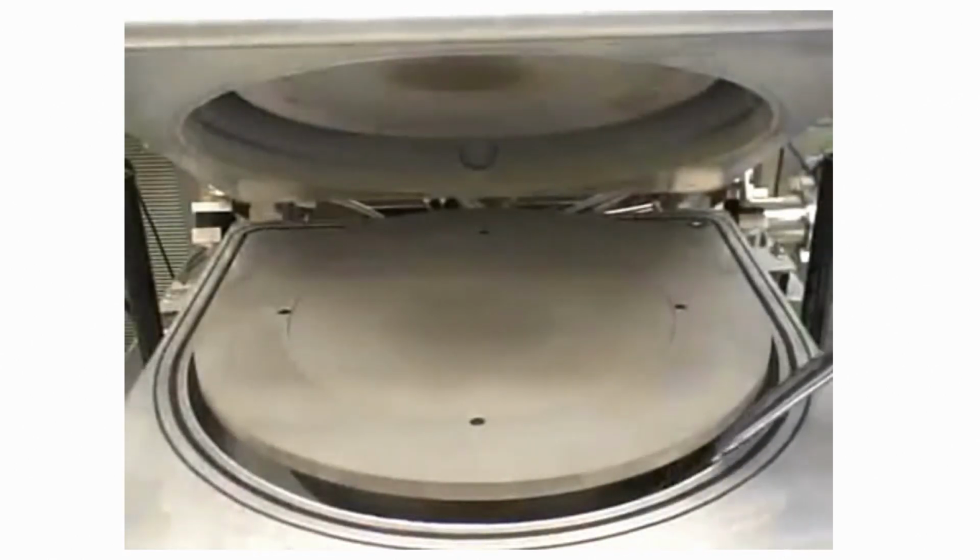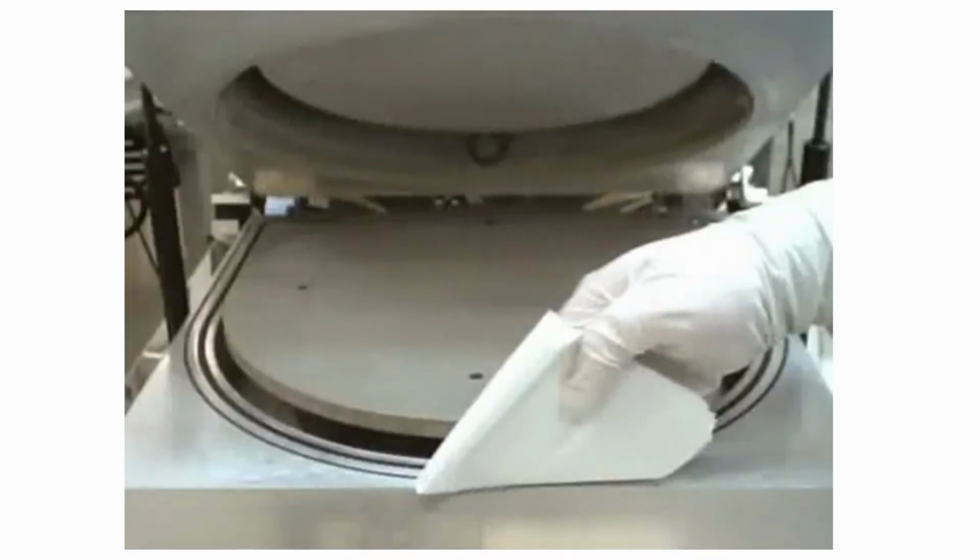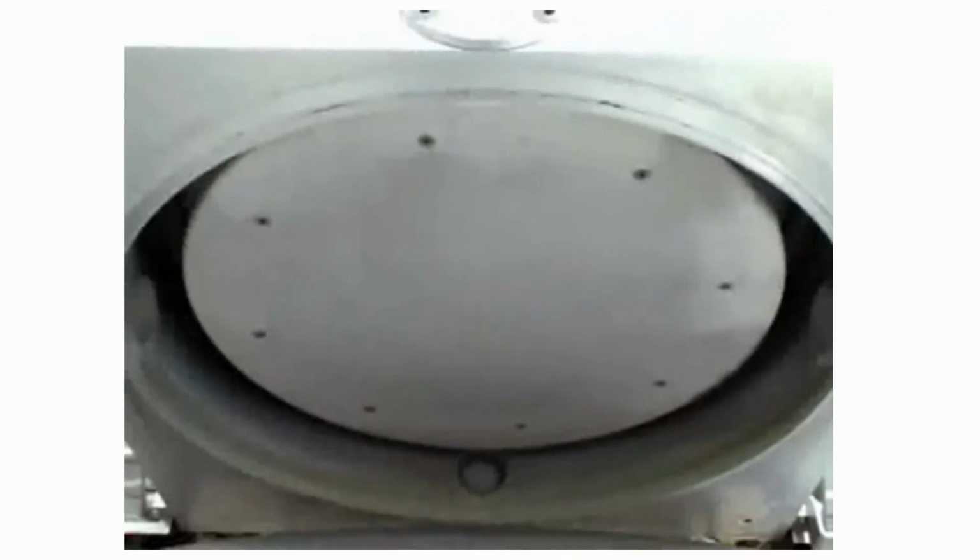Do not vacuum the rubber seal because this could cause it to become damaged. Instead, wipe the area around the seal with a tex wipe. Under no circumstances should you ever touch the shower head. If you happen to notice material flaking onto the platen from the shower head, you should notify an MRC staff member so it can be cleaned manually.